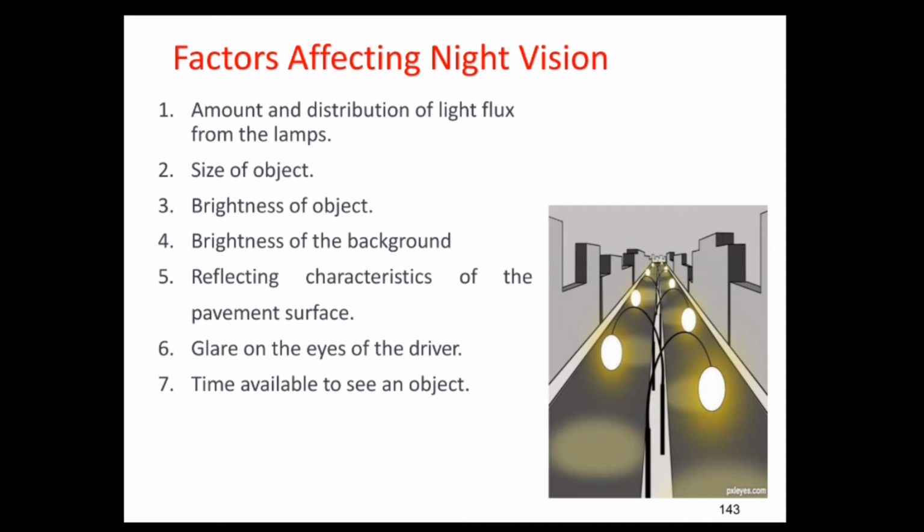The white topped pavement or concrete roads have good reflecting characteristics as compared to black topped pavement, that is, bitumen pavement, as on concrete roads the light from the street lights or the headlight beam of the vehicle gets reflected, thus causing better luminance.